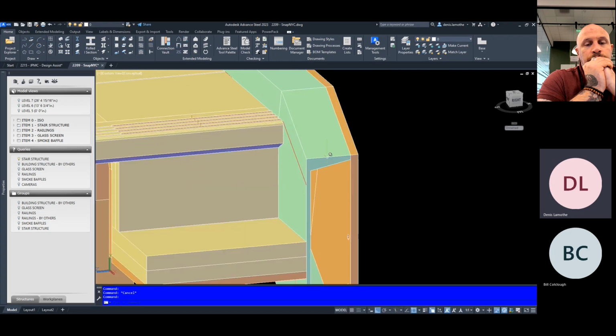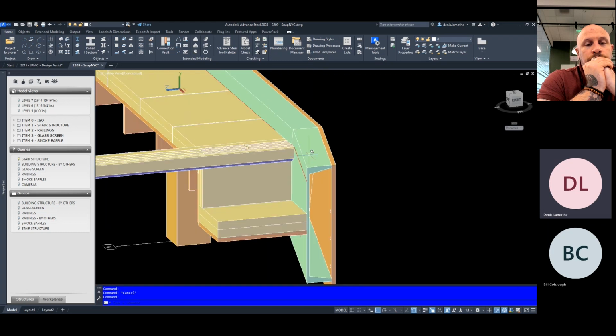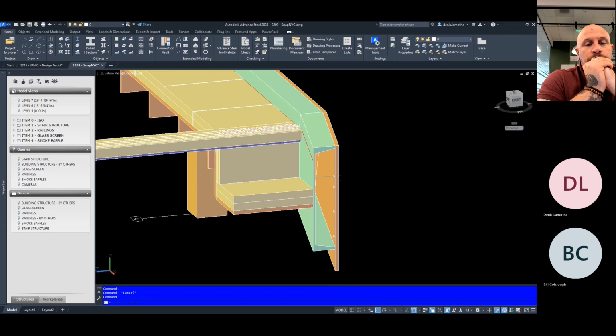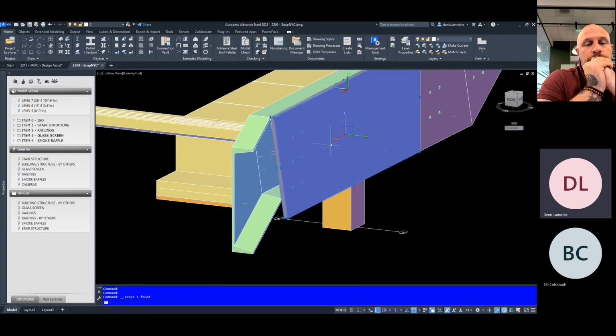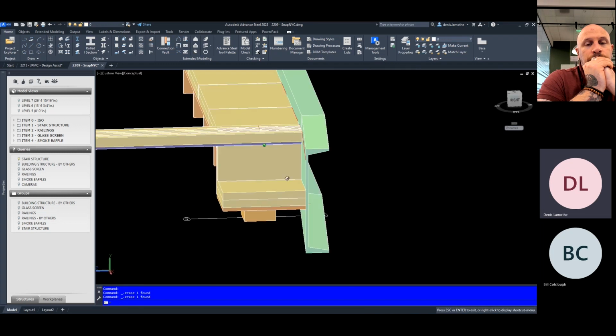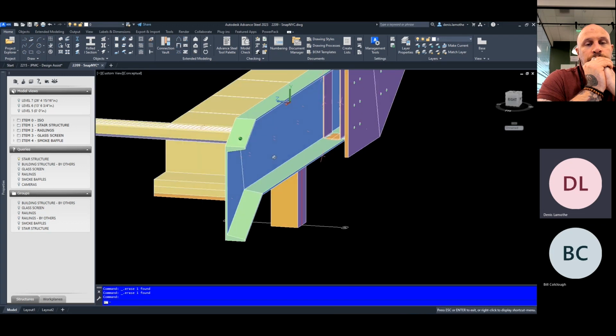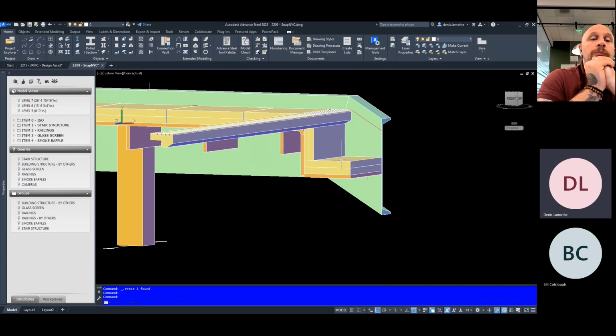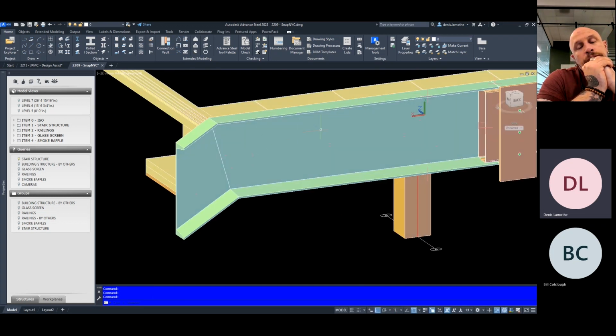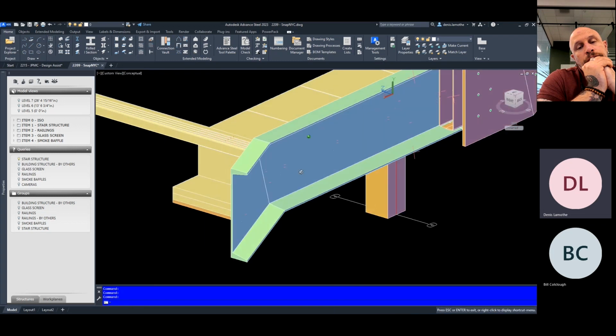So again, we have a nice big flat surface on the channel. It's great for welding posts, flat bars, or anything else in terms of railings. And the downside to it would be that any connections, if it's a bolted connection for whatever reason between the tread and riser plates or any other element, maybe a splice joint that would require a splice plate, if it's bolted, you're going to end up seeing the bolt heads on the other side of the web that's exposed.